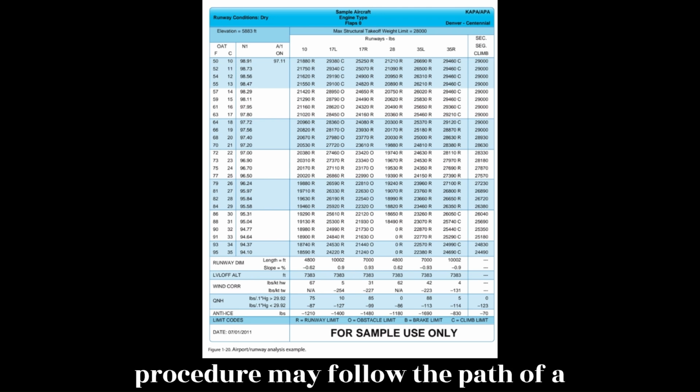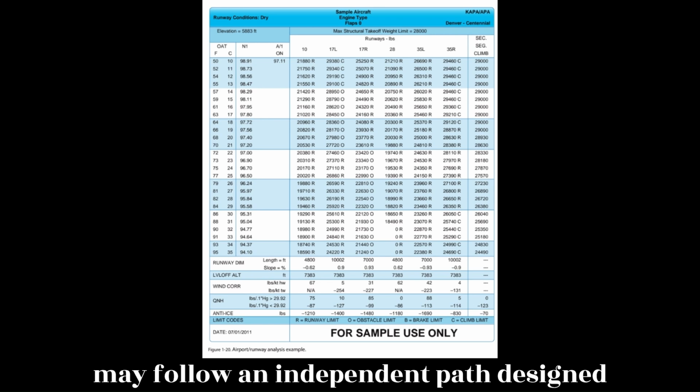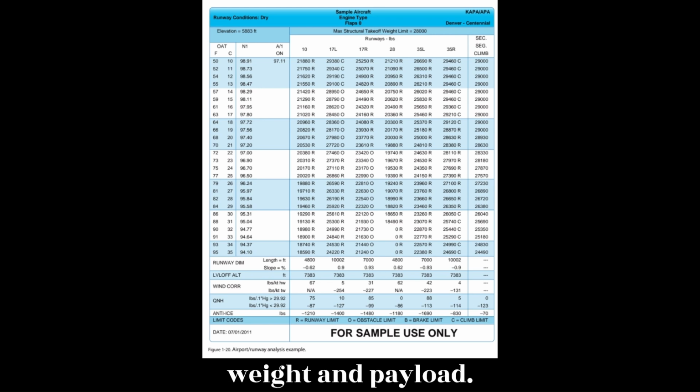This OEI turn procedure may follow the path of a published IFR departure procedure, or it may follow an independent path designed to avoid otherwise onerous obstacles and thereby maximize the allowable takeoff weight and payload.